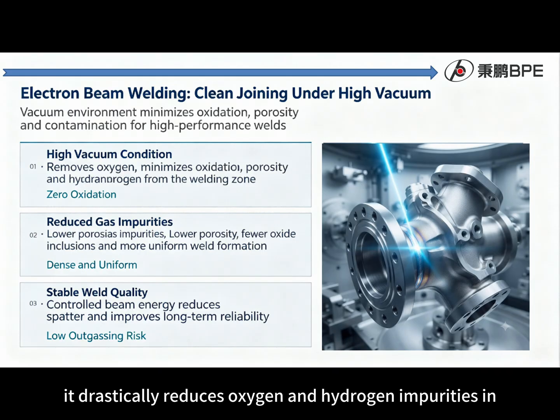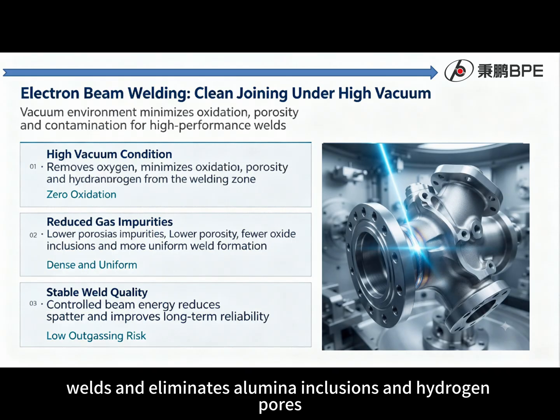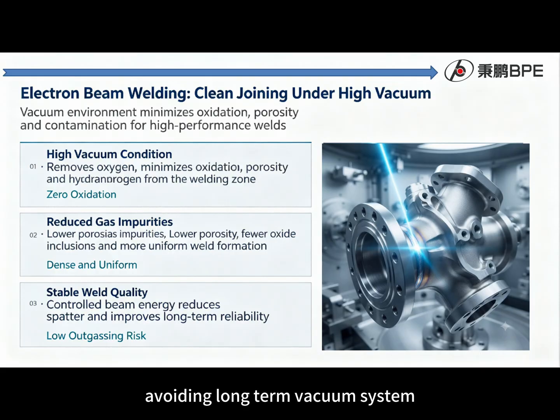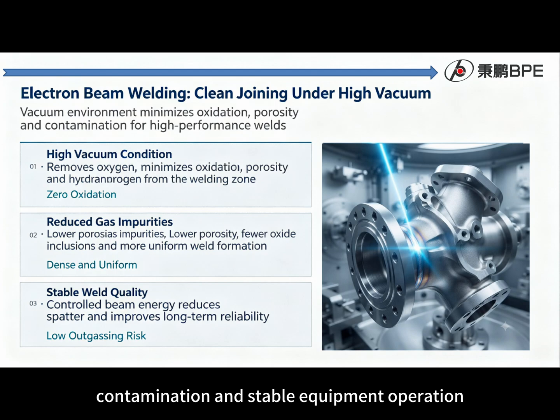It drastically reduces oxygen and hydrogen impurities in welds and eliminates alumina inclusions and hydrogen pores. Welds feature dense microstructure and low outgassing rate, avoiding long-term vacuum system contamination and ensuring stable equipment operation.